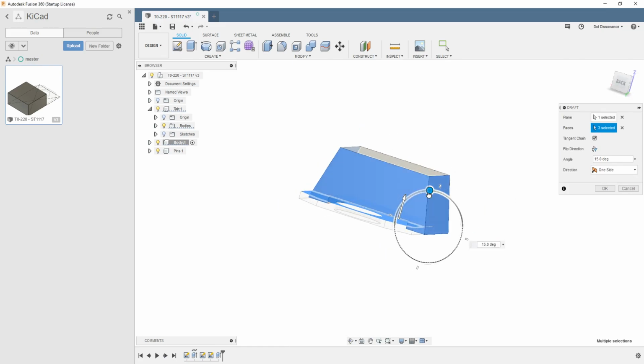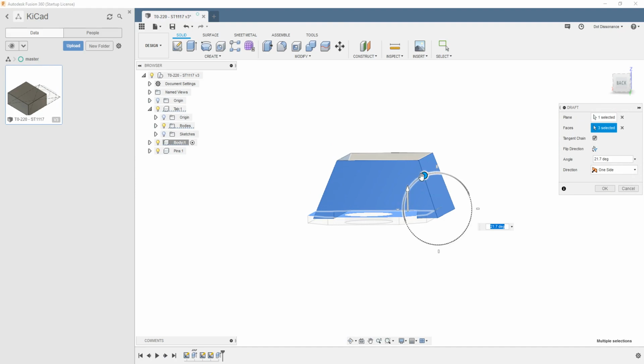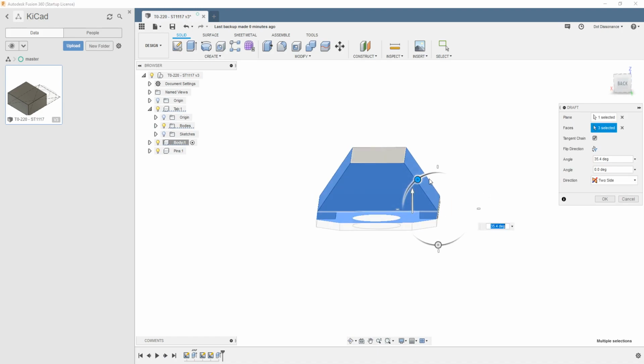It bends. Can you see pivots on that plane right there? But you see, I don't want this other bit here sticking out, right? And so in, say, CATIA, other programs will have parting elements and limits and things. You can just say not to do that. But the way you do it here is you pick two sides and just leave that side at 0, and it'll get you the same effect.